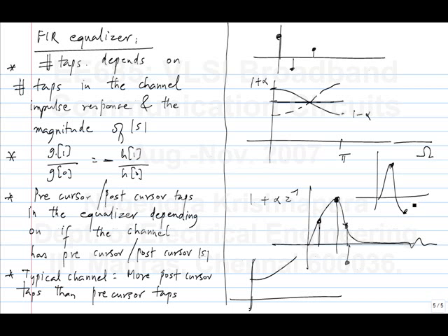But in practice, we are already so short of bandwidth that we don't see responses like this. If anything, we will see something of this sort. So what does fast alternation mean? That means high frequencies, right? So that means the output has a boosted high frequency. So this won't happen. And more likely, what is going to happen is it takes a long time to die out. So because it's a low pass channel, you can't have it. That's all. It's not because of any fundamental limitation. You could potentially have negative postcursor and precursor.